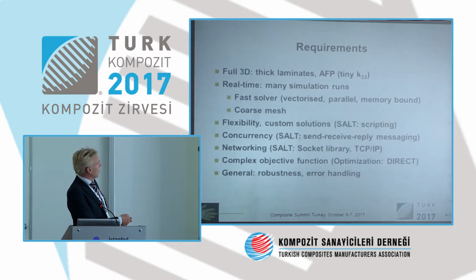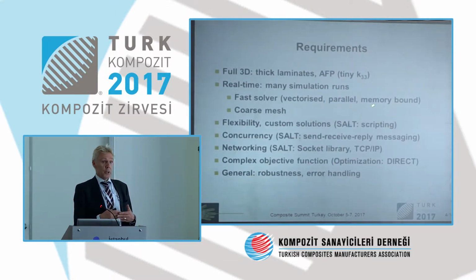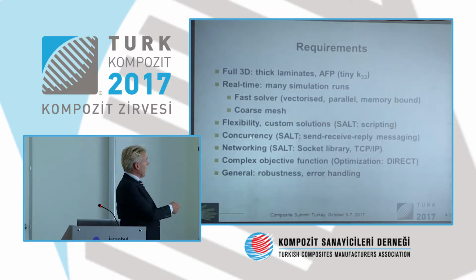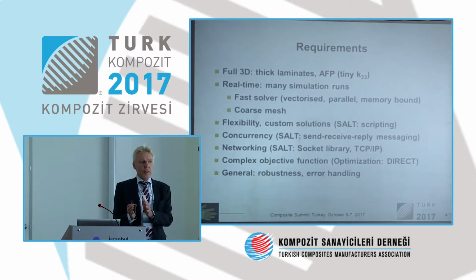Because we have to do many simulation runs in 3D, we need a very fast solver. So that's the first area where we put in a lot of effort. The solver is vectorized, so it can work in parallel. However, we are limited by the speed of the memory bus, the connection between your CPU and your memory. This is what limits the speed of the solver. So we hit that limit now, so we cannot go much faster unless you buy faster hardware, of course. And we have to work with coarse meshes. We cannot afford to use very detailed meshes, because if we do, it slows down too much and we are no longer real time. So we also need to be very flexible, because a flow analysis software can be a single application running on one computer. However, when we connect with the sensors, we suddenly have to interact with the outside world.